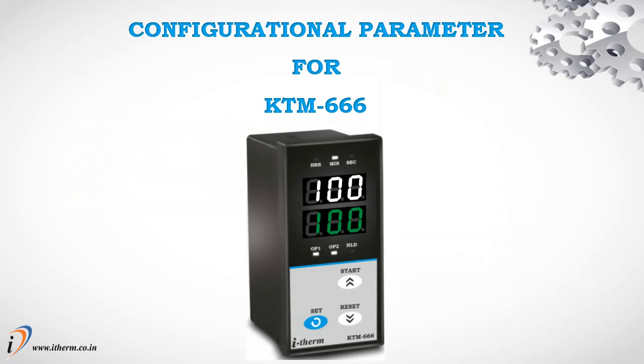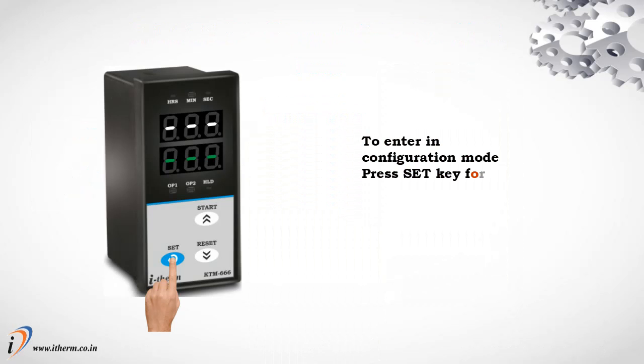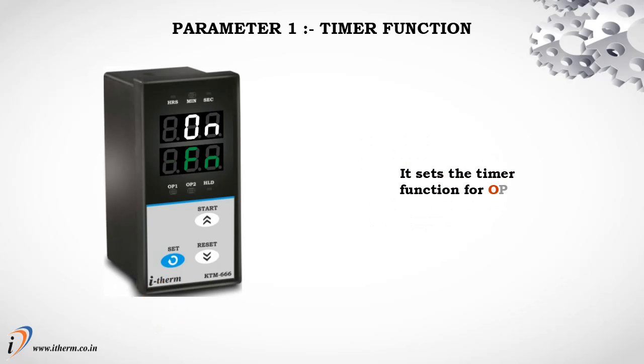Configurational parameter for KTM 666. To enter in configuration mode, press Set key for 6 seconds. At power on, version number will be displayed. Parameter 1, Timer function. It sets the timer function for output 1.